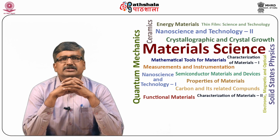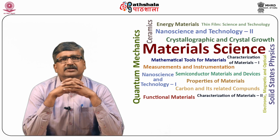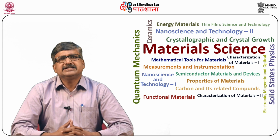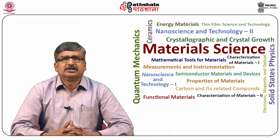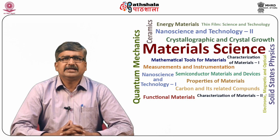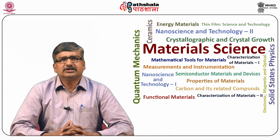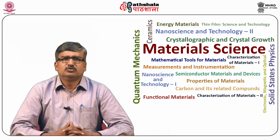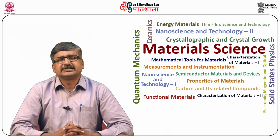Large quantities of pure CNT can be made into a fiber filament by wet spinning method. The fiber is either directly spun from the synthesis pot or spun from pre-made dissolved CNTs. Individual fibers can be turned into a yarn. Apart from its strength and flexibility, the main advantage is making an electrically conducting yarn. The electronic property of individual CNT fiber, a bundle of individual CNT, is governed by the two-dimensional structure of CNT. At room temperature, CNT fiber has a conductivity one order of magnitude higher than the best electrical conductors.